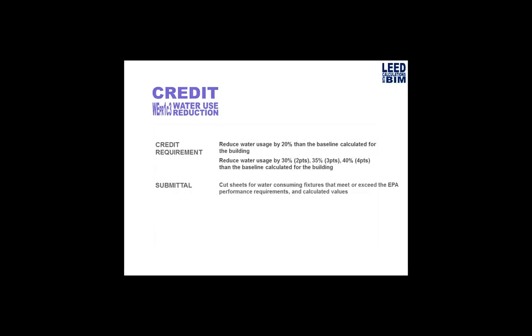So the water use reduction credit seeks to reduce water usage from a baseline by using high efficiency fixtures. The prerequisite, which you have to do, is to reduce the water usage of your building by 20% off of the baseline case. And then you get extra points with credit 3 if you can provide further reductions of 30 to 40%.